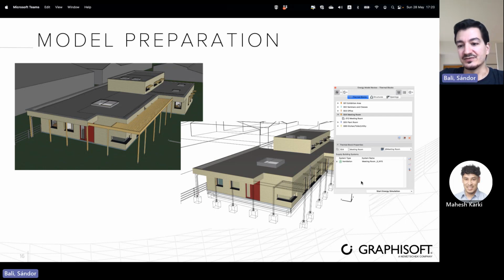So what we're going to also do is that we have these visual filters, which is also really just to help us to differentiate things visually. But to have this logical connection, we're also going to set up the so-called thermal blocks, which is going to mean that we're going to collect zones and spaces into thermal blocks, primarily based on their function. So you can see that the meeting room thermal block contains a meeting room zone. But of course, it's not only one zone per thermal block. It could be various zones per thermal block.